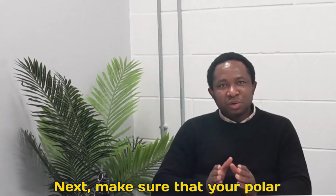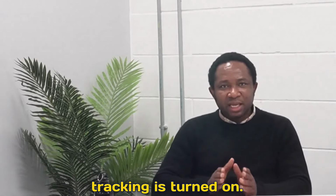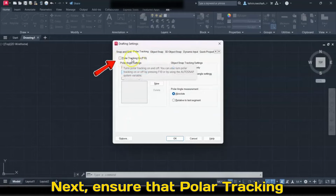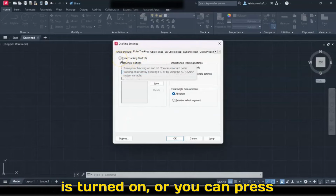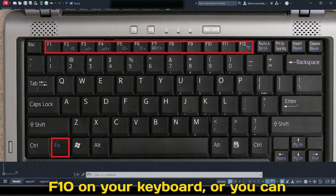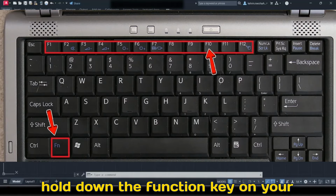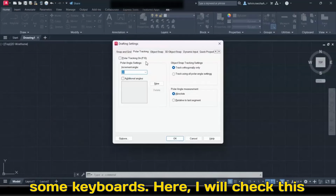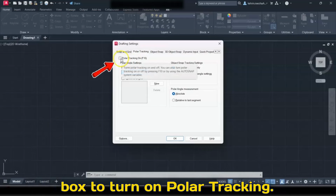Next, ensure that polar tracking is turned on, or you can press F10 on your keyboard, or you can hold down the function key on your keyboard before you press F10 for some keyboards. Here, I will check this box to turn on polar tracking.